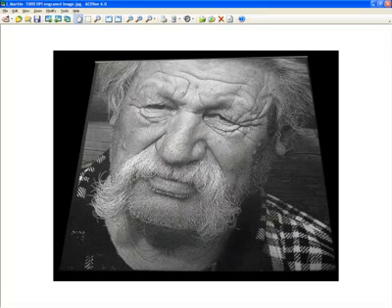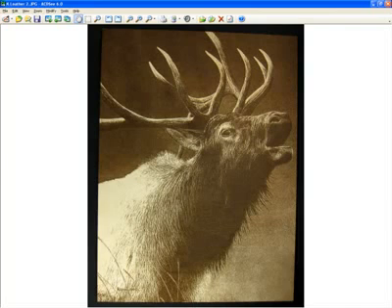Now, if you want the absolute best results, the high density or HPDFO lens is preferred for best photography type engraving. But a 1.5 is the next best, followed by the 2.0, all of which can be done. Most of the samples I will run are run on a 2-inch lens just to show you that it can be done. For example, this nice leather picture was done with a 2-inch lens, no problem.